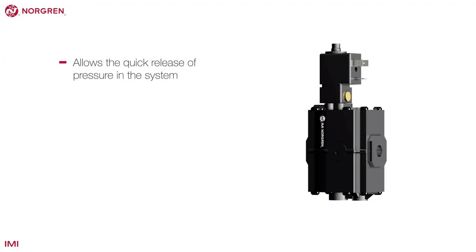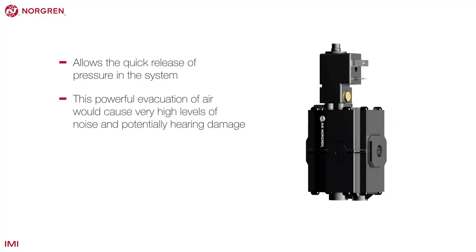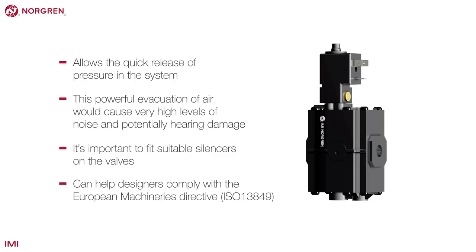A dump valve allows the quick release of pressure in the system, usually in emergencies. This powerful evacuation of air would cause very high levels of noise and potentially hearing damage, so it's important to fit silencers on the valves.